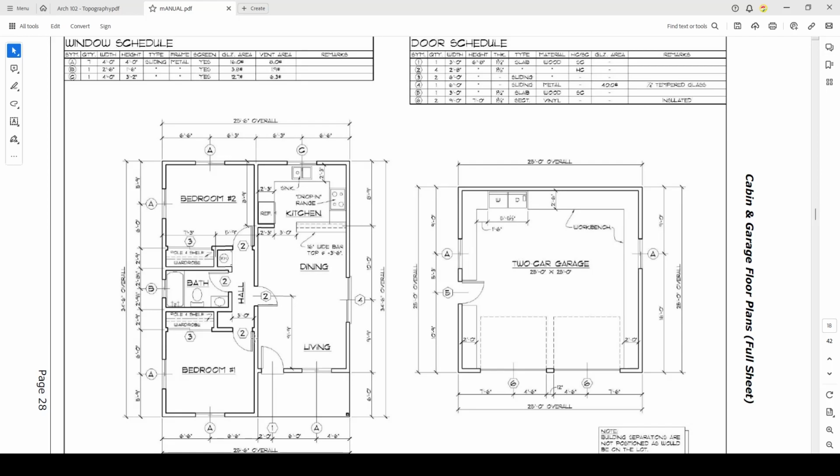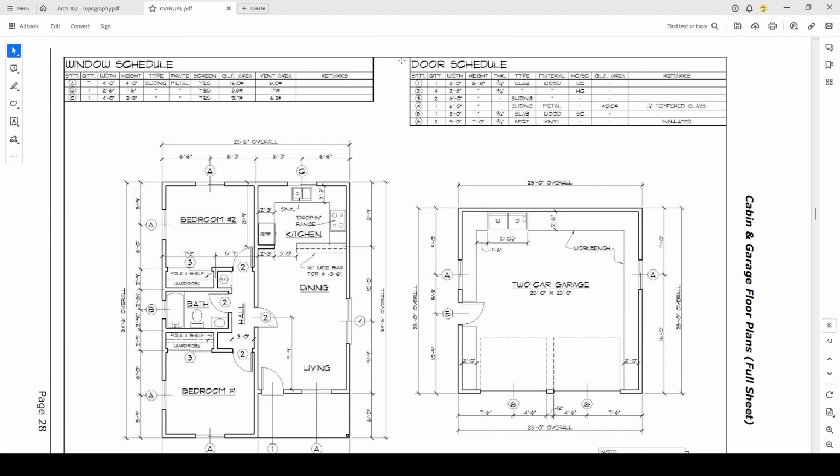When doing doors and windows within Revit, I highly suggest sticking with either doing doors or doing windows, but not swapping between the two. If you are working off of an already developed floor plan, like what I am showing you, do your doors first and then do your windows second. But again, do not swap interchangeably between the two of them. Focus on one thing at a time. So we're going to take a look at our door schedule.